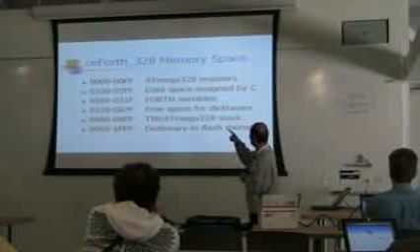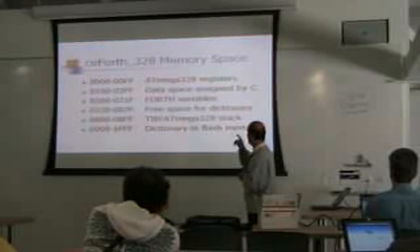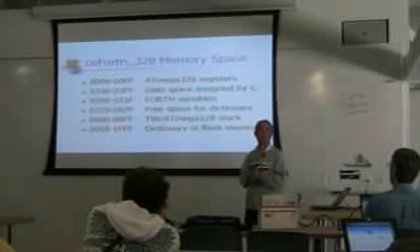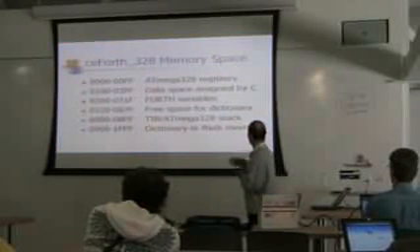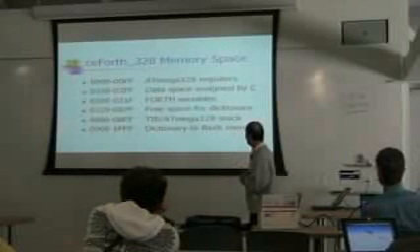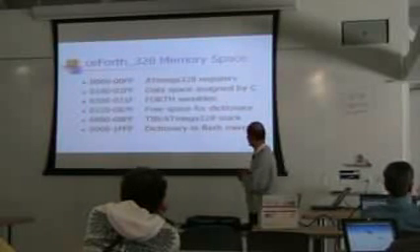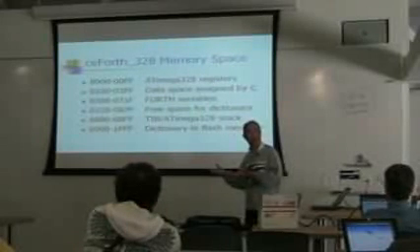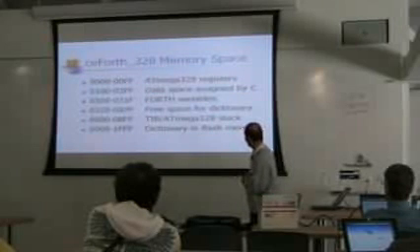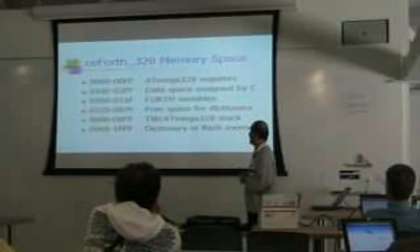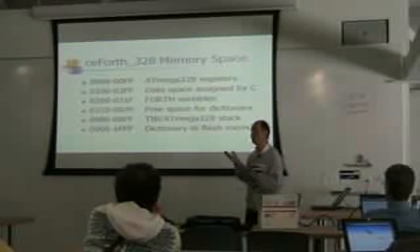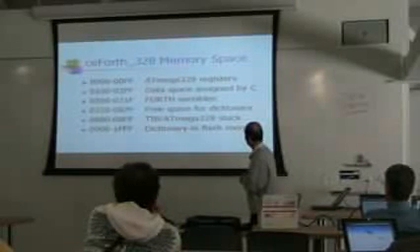From 100 to 2FF is a data space assigned by C, so I have no way of knowing what's in it. But I looked in the memory map, and I didn't put anything there, so it must be put there by the C compiler. From 300 and up, that seems to be free. I poked and peeked, and nothing serious happened.